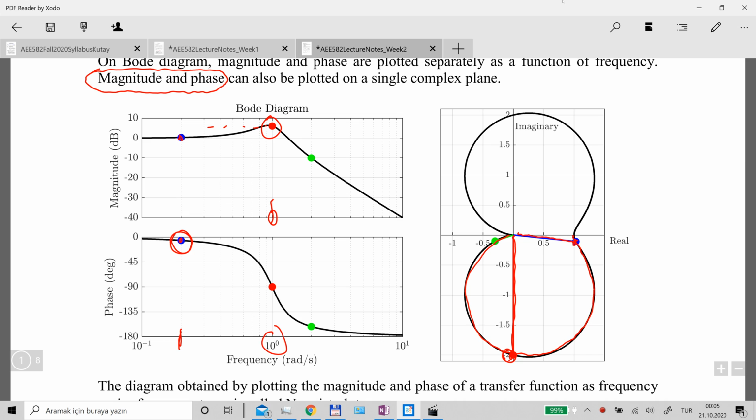Well, I think the Bode diagram can also give you the stability margins provided that the open loop system is stable. But in the case of the Nyquist diagram, even when the open loop system is unstable, you can still conclude the stability of the closed loop system and its stability margins. Well, if you are curious about this difference, I can provide you some references where you can read more about the details. But the Nyquist diagram is more powerful in terms of assessing the stability and robustness of the system.